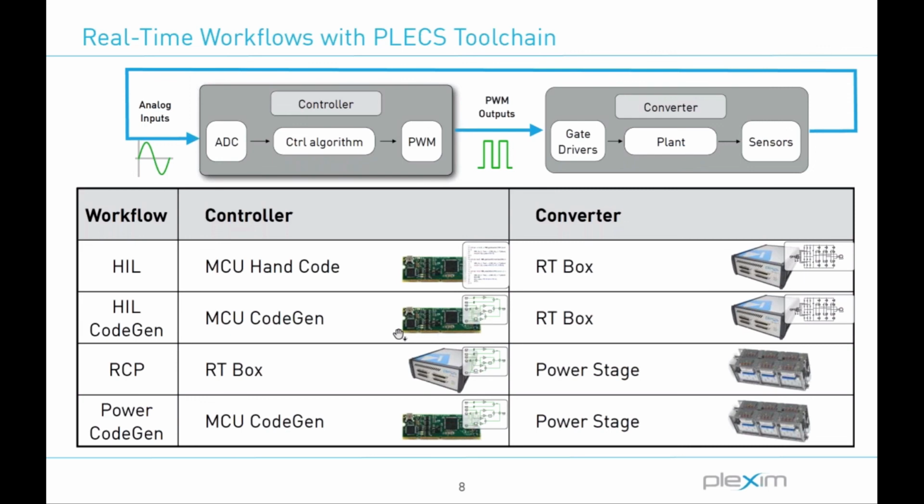Perfect. If you do have any other questions, now's the time to ask them. A question we've received before has been about phase shifted PWMs, and I think anyone can answer this, but within PLECS, within the target support package, there is a special block called the variable PWM block, which will support generated code for phase shifted PWMs.